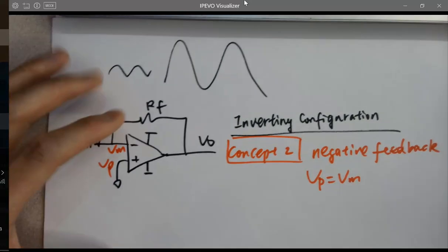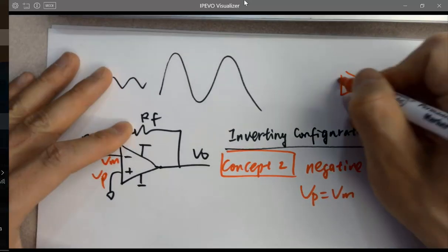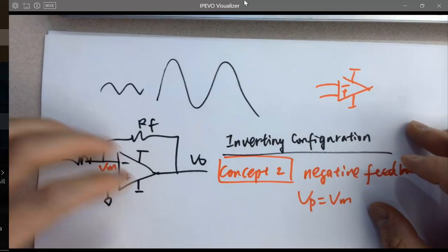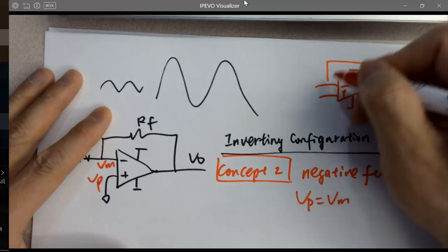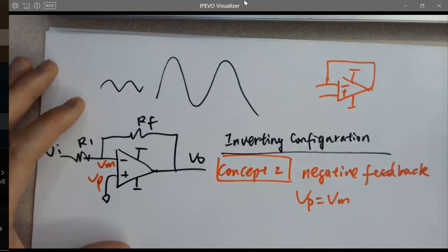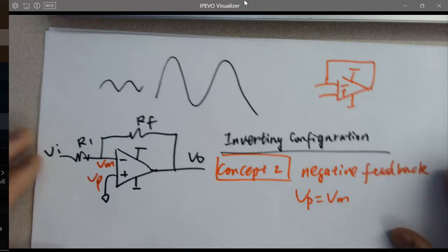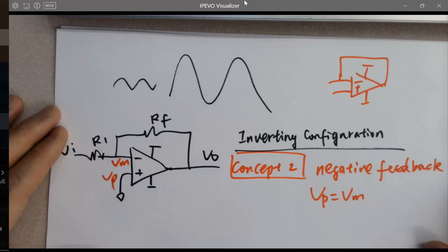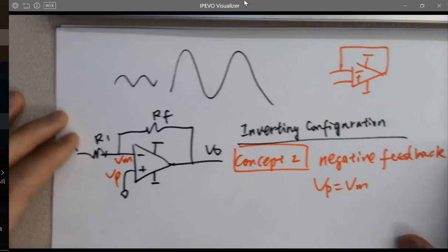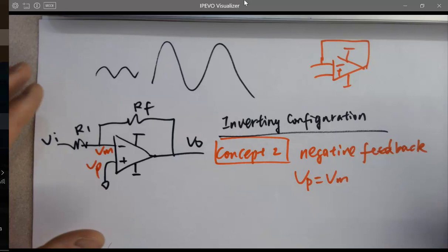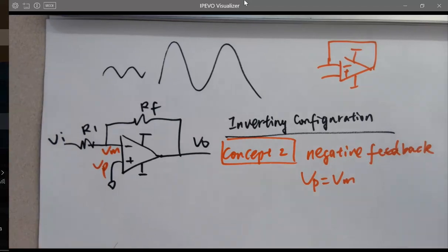If you just grab an op-amp from the drawer, are they going to be equal? No, they're just two different terminals of the op-amp. It won't be equal. You have to do some sort of negative feedback to make it equal. And 99.99% of the time, you are using negative feedback, never positive feedback. If you do something wrong, your mom should tell you no, that's wrong. Positive feedback is like your mom encouraging you to do more of it. It's going to keep going and then saturate. It won't work.